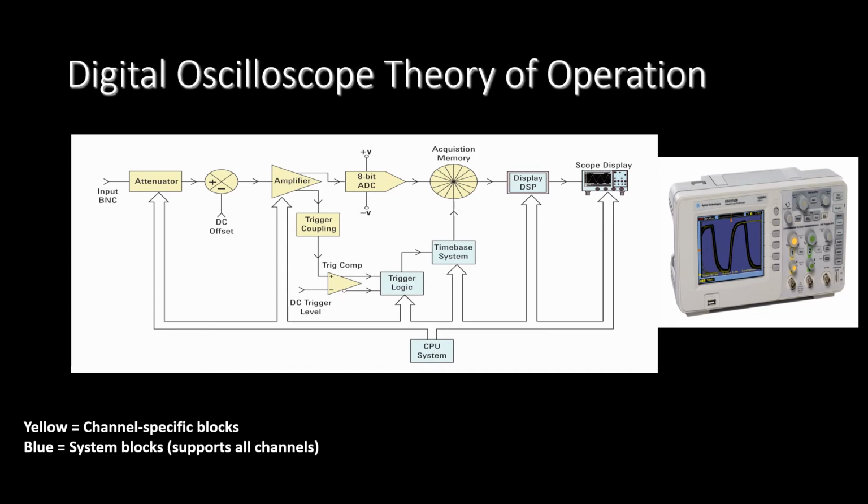Many of today's newer digital oscilloscopes use dedicated and custom built digital signal processors to quickly process digital filters and then effectively pipeline the waveform data into a display memory to thereby improve the throughput and waveform update rates.